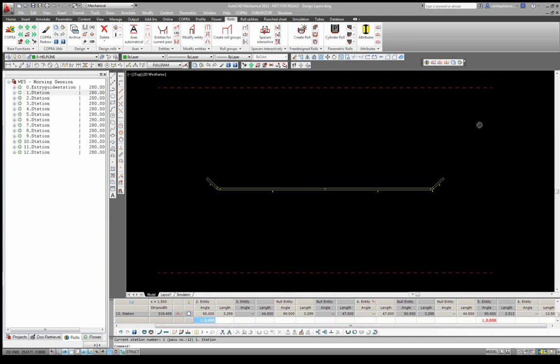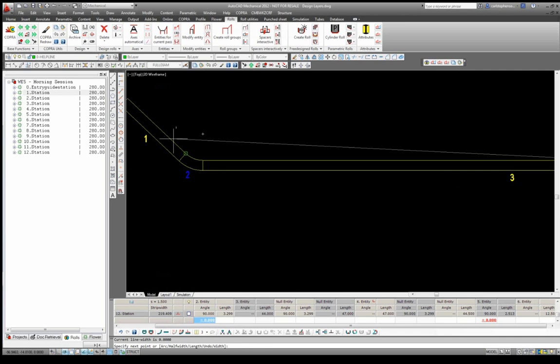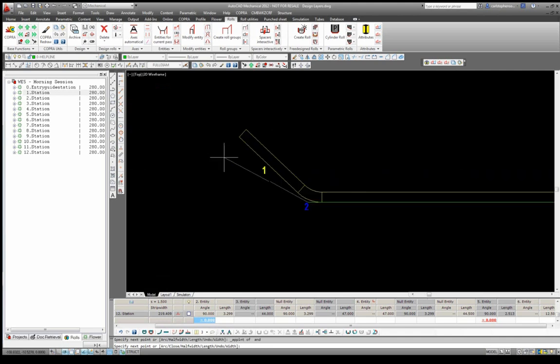So first of all, I will create a bottom roll using the free design functions. Now essentially, to do this, we need to create a polyline of our bottom roll. We have several ways to do this. We can of course draw one by using the polyline feature over here in AutoCAD, which will take the polyline from here to the apparent intersection of here to here. So I can draw a polyline in this manner.